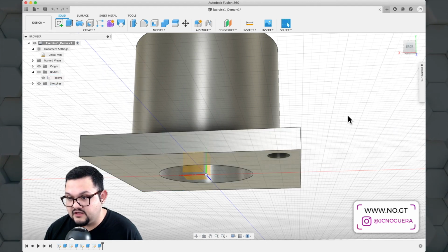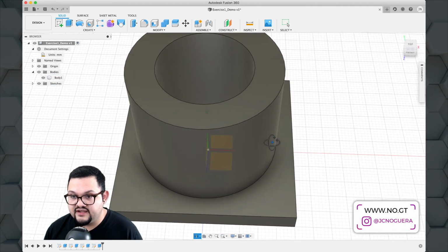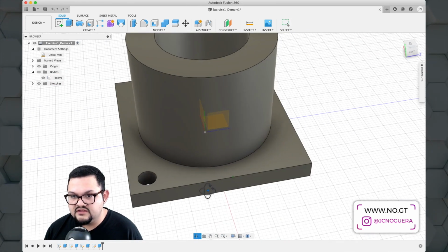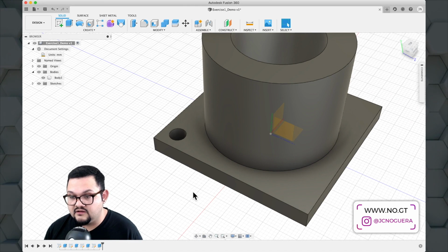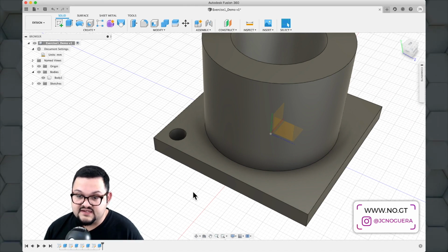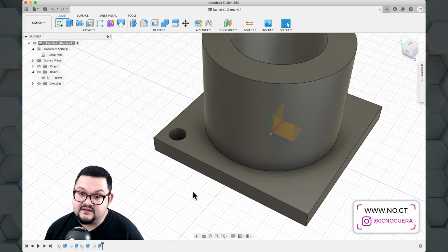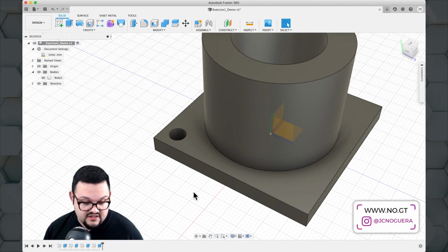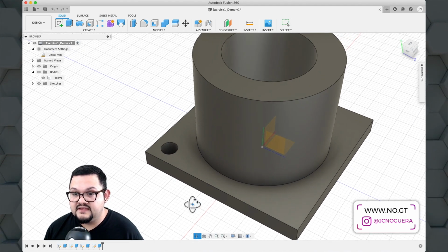I'm going to select OK. Now I've generated a hole in one of the corners, right? So we can repeat the same operation on all 4 corners, or actually do a sketch that has all 4 holes, and we can do a single extrude operation by selecting the multiple areas inside the circles. But I can also use other tools to repeat this hole.